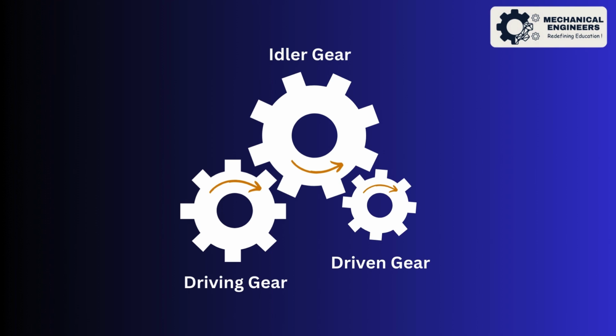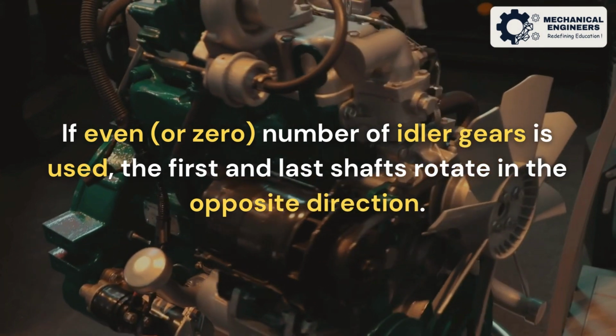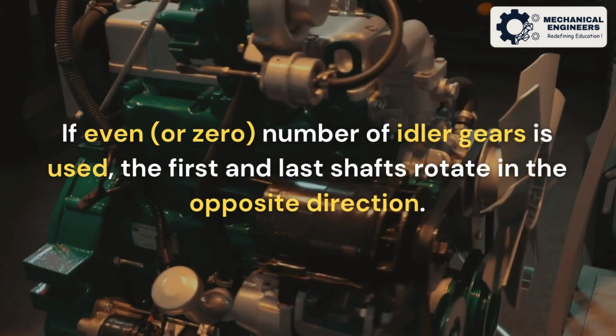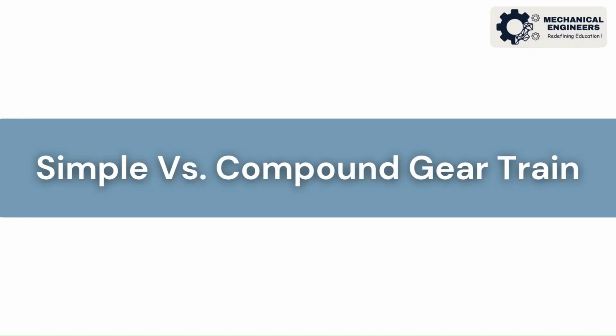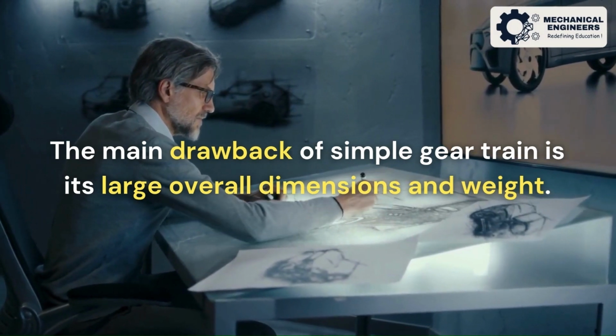Now, if you introduce an even number of idler gears, or even none at all, the scenario changes. In this case, the first and last shafts rotate in opposite directions. Imagine two idler gears in between. Each one flips the direction of rotation, leading to a complete reversal by the time you reach the last shaft. The main drawback of a simple gear train is its large overall dimensions and weight.